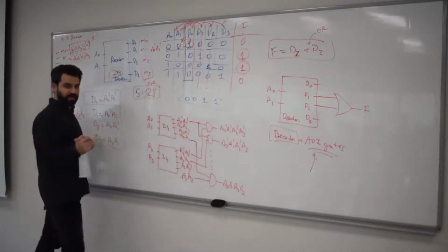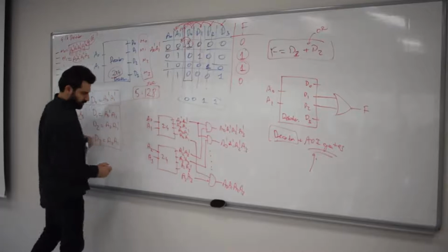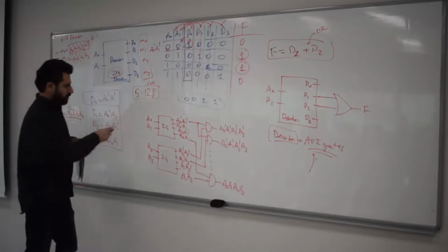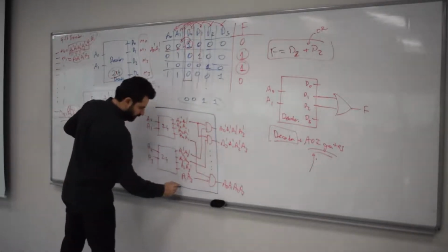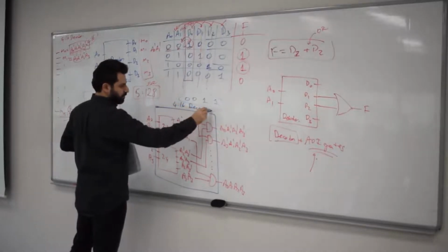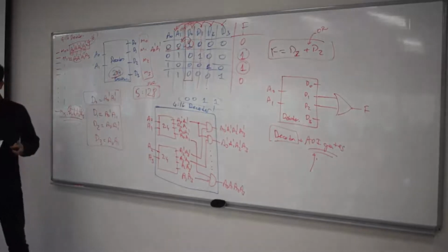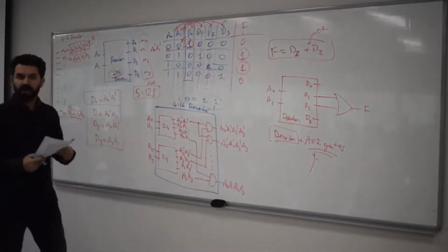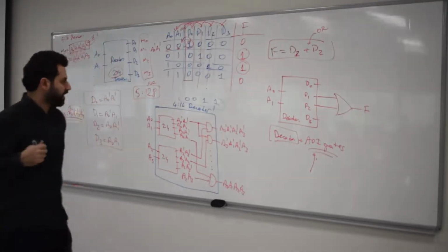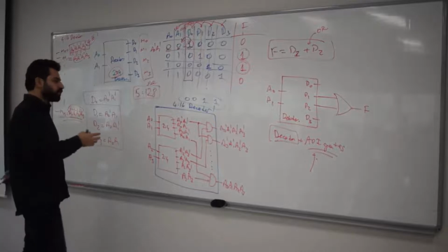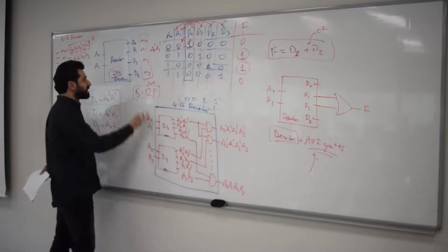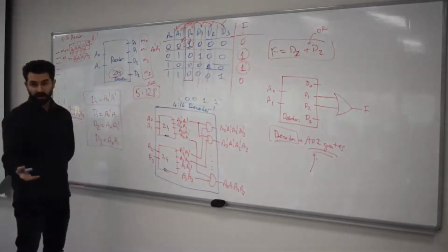So therefore, if you just put these wires a little bigger, you will realize that this bigger circuit now is your 4 by 16 decoder. All right? This is hierarchical design. We did not, for instance, apply our design logic based on Karnaugh maps, AOI gate technology. This is a different design because now you're using smaller blocks to come up with a bigger block that does exactly the same thing, but the number of inputs and outputs is higher, bigger.